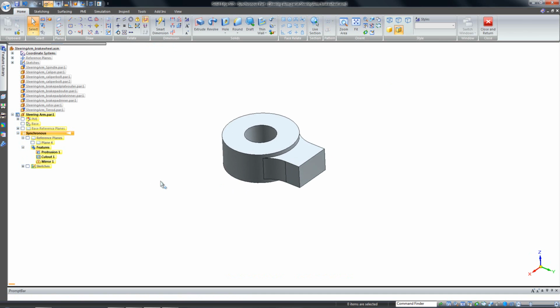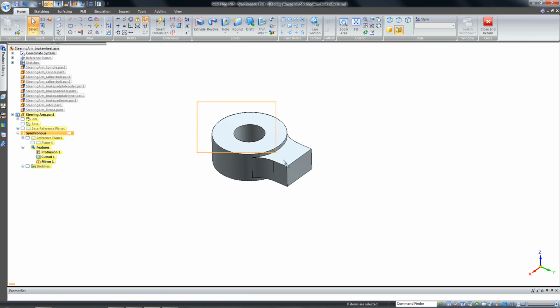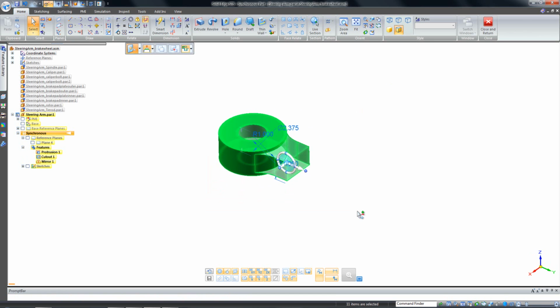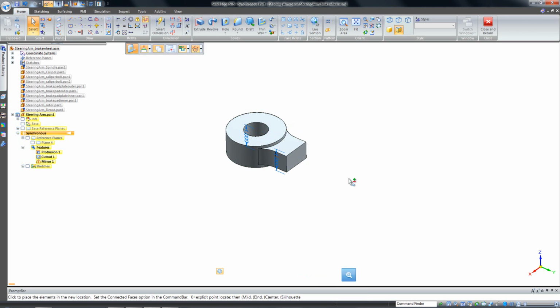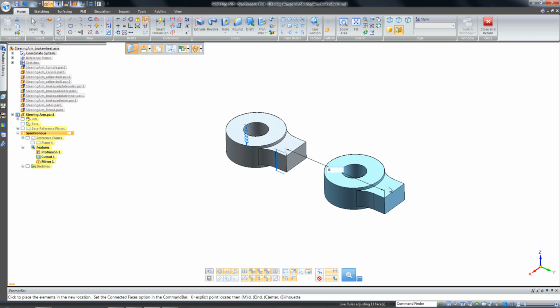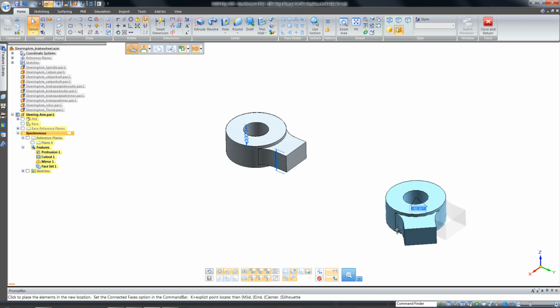Again, replicating geometry in synchronous is a very easy thing to do. So again, I can just window select around what I have, and I essentially want to take that geometry and just copy it. I can hold down the control key on my keyboard, specify the direction in which I want to copy, and I just want to copy that out 8 inches. I also want those two to face each other, so what I'm going to do is I'm just going to place my steering wheel at the center of the hole and then just tell Solid Edge to rotate that around 180 degrees.